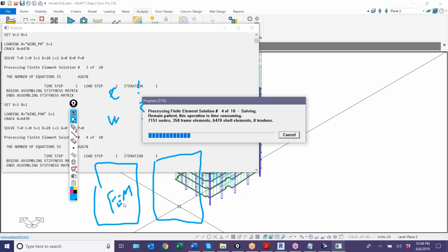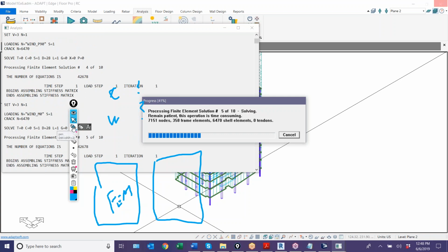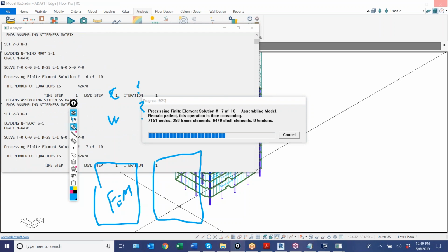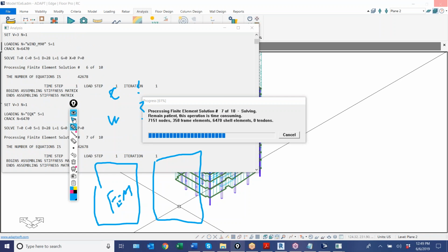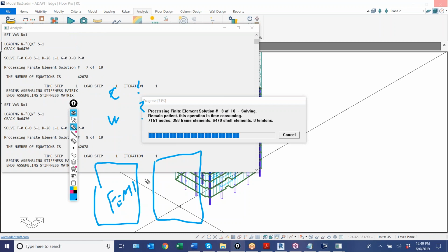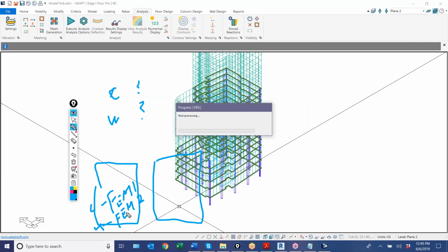So those are the finite element results for this global run. If I run it a second time with uncracked, this basically gets overwritten in terms of its availability for direct FEM results that you can navigate within our interface. In terms of design of walls and columns, if I run FEM once, I'll call this FEM1, and that's the usage case that we selected for column design lateral. I run FEM twice, and this is now the usage case, I'll call this FEM2. This is the uncracked usage case. This is the cracked usage case, essentially.